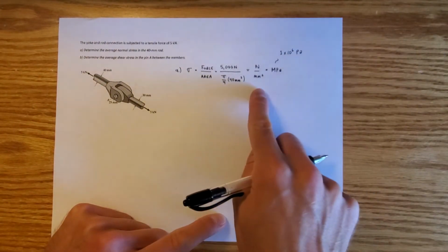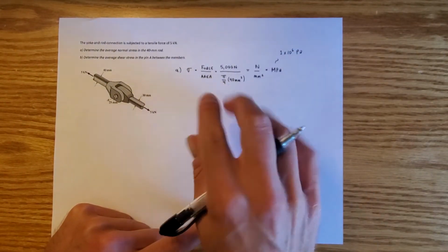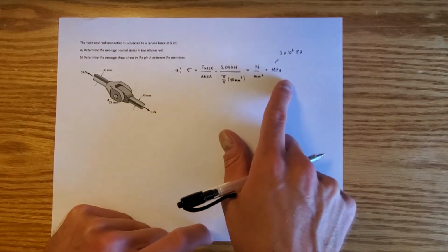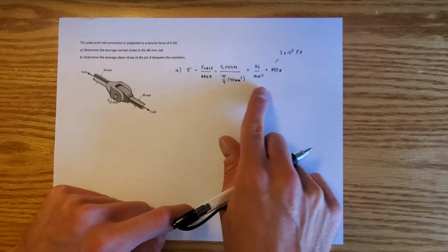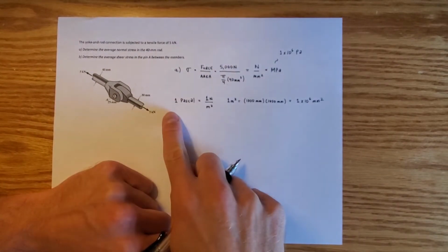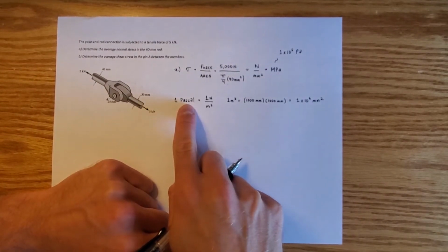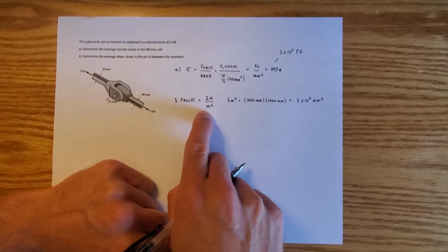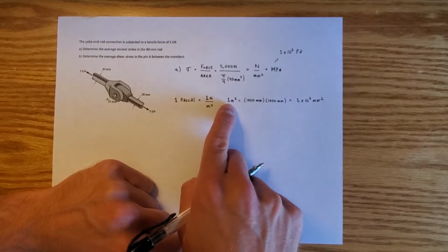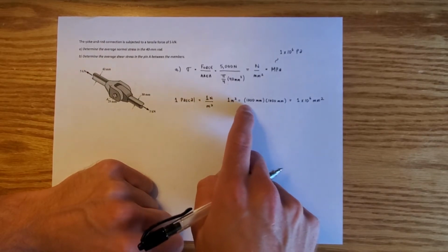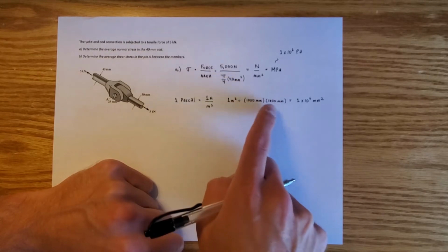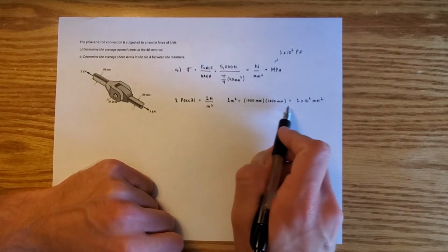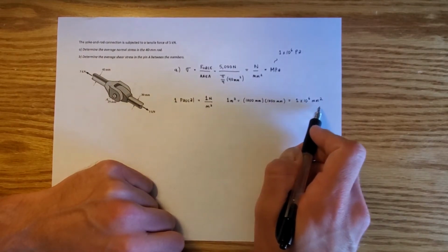This is a cool trick with units. That way you don't have to convert this to meters and then back into other things. You can just do all your math real quick and get megapascals out. And let me show you exactly why this works. So what we can see is that 1 pascal is force over area and is usually 1 Newton per meter squared. We know that 1 meter squared can be represented by multiplying 1,000 millimeters, which is 1 meter, times 1,000 millimeters, which is also 1 meter. So this tells us that 1 meter squared is equal to 1 times 10 to the 6th millimeters squared.